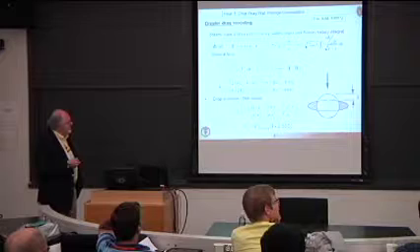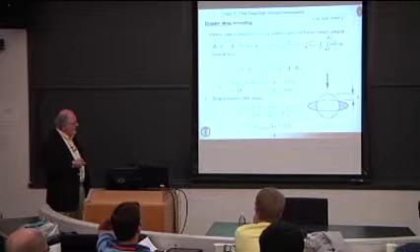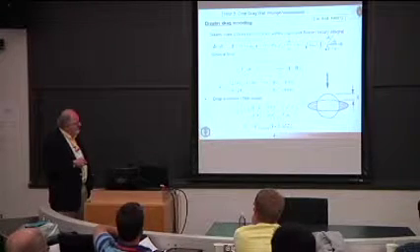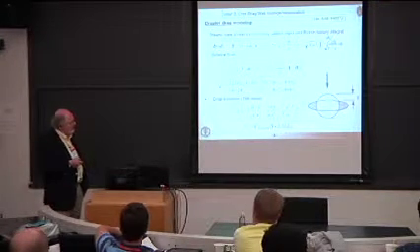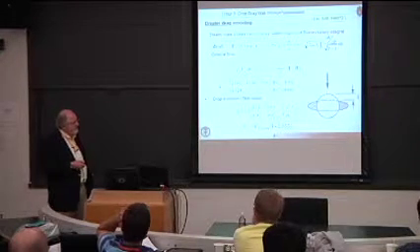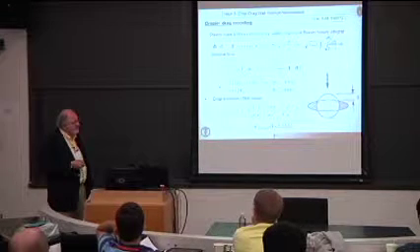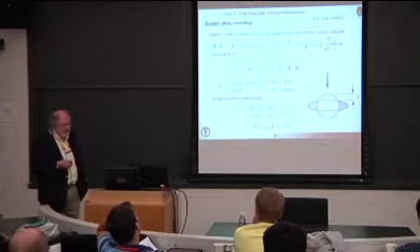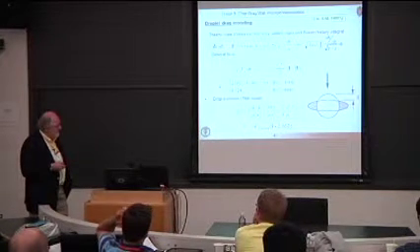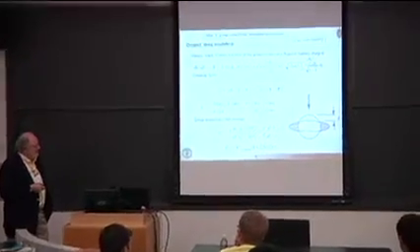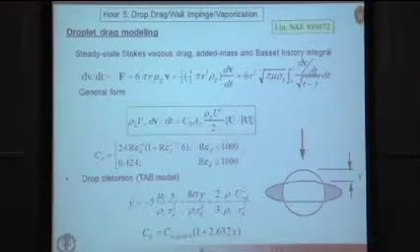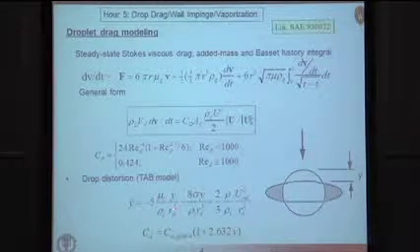Okay, so how do you take into account other effects such as the distortion of the droplet? Again, Taylor in the 1940s proposed this Taylor analogy model, where essentially he calculates the distortion of the droplet, and this parameter y here is a non-dimensional distortion, non-dimensionalized by the radius of the drop. Here is his governing equation. It's a second-order ordinary differential equation. The inertia term on the left-hand side. Here's the viscous damping term. You see the liquid viscosity, the liquid density, the radius of the drop.